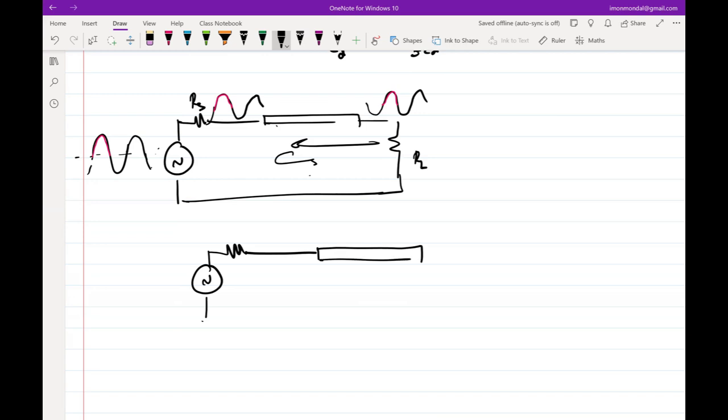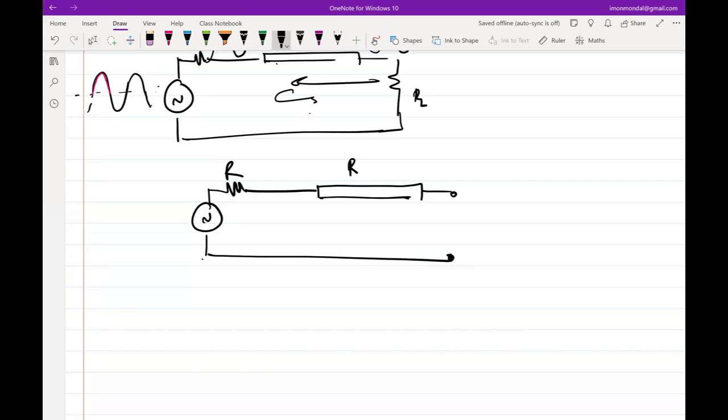Let's say I am just taking a matched transmission line. Let's say this is R and this is also R. And this is open circuit here, right? And you apply a sinusoid. And again, let's say I am riding this crest. So at time t equal to 0, what will this waveform be? If this is 2 Vp, what will be the time t equal to 0 waveform? It will be Vp, right? It will be divided by 2 at time t equal to 0, the forward going wave, right? So essentially it will be exactly aligned with the input, but this will be Vp.